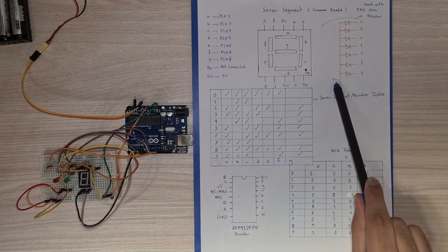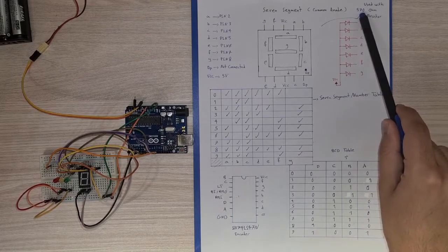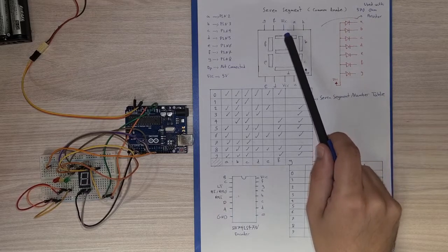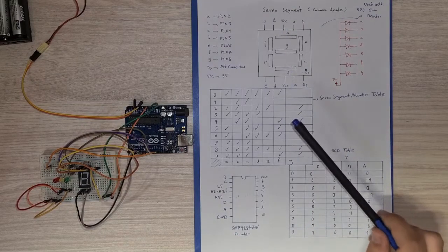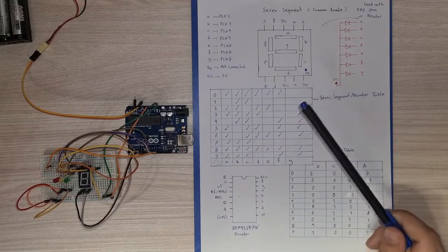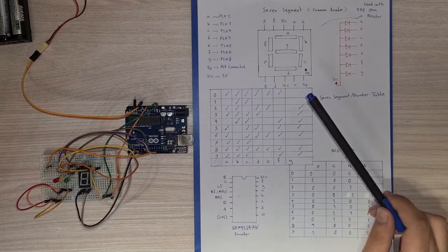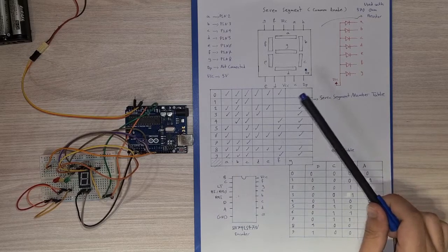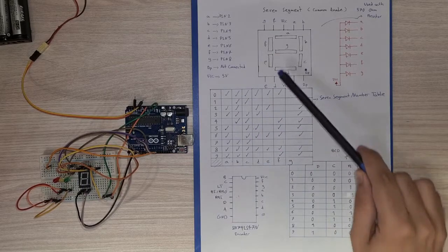So this pin that contains all the anodes of the LEDs is here, one on the upper side and one on the downside. It doesn't matter which one of these you connect to Arduino, to a battery, or to the 5 volts of Arduino. You can connect just one of these. It doesn't matter if you connect 2 of these or just one.